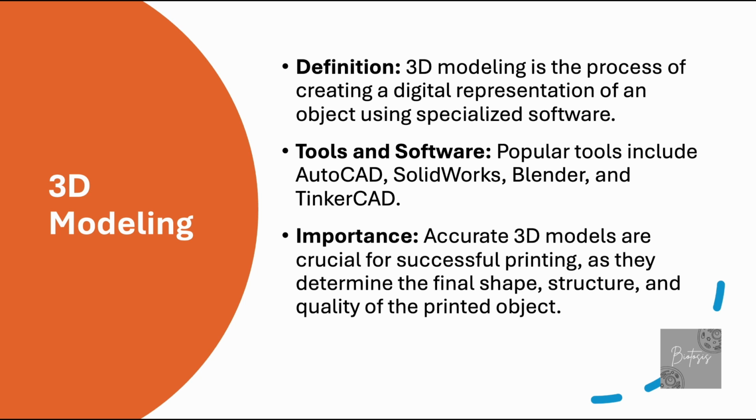The dimensions, right? The layer thickness is what we have to make sure of. While we are creating a model, we also have to keep in mind what ink we are going to use, because sometimes if we say we want 1 mm thickness and our ink is very fluid, the viscosity of that ink is really very low, so 1 mm will be very difficult for it to hold. It will be much less. So those are the things that need to be considered before and while creating a model.